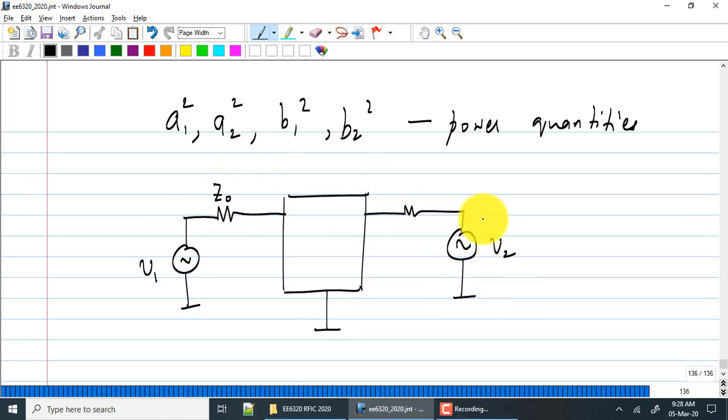The two-port itself may not be matched, right? But if I want to measure the S parameters, I would drive it with a 50 ohm matched source. I cannot drive it with an ideal source. Because if I drive it with an ideal source, since impedance is not, you don't know what the input impedance of your circuit is. But you want to make sure there is an incident power, not an incident voltage. So that's why you characterize it when everything is driven with 50 ohm systems.